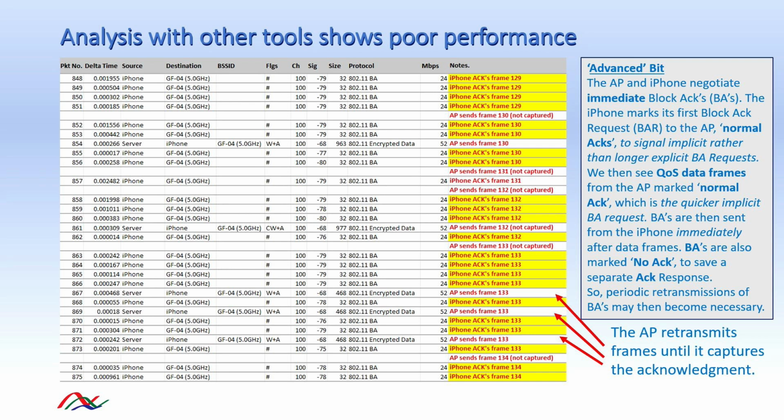So whilst the heat map looks good, it doesn't show the signal strength the AP is getting from the client. The received signal strength from the client should be taken into account so that there's good two-way communication within AP cells, and this is how Wi-Fi needs to be designed.